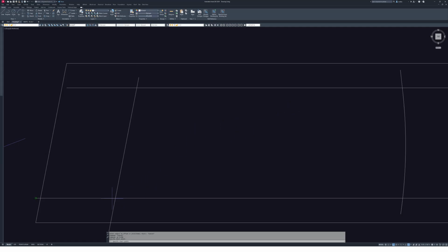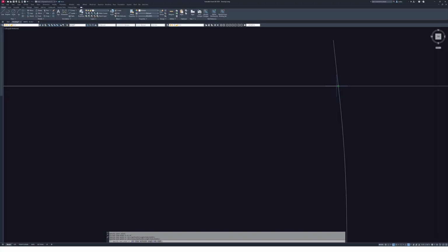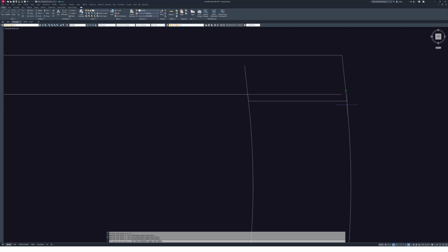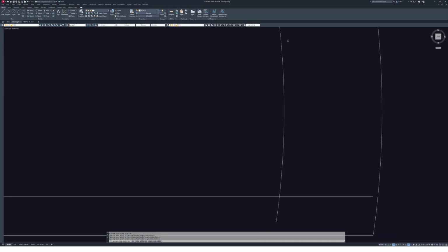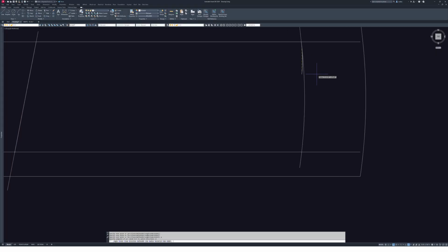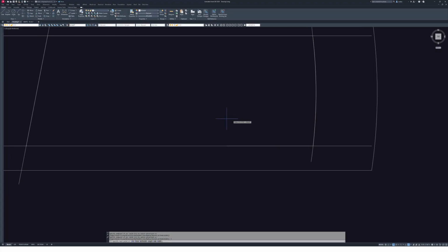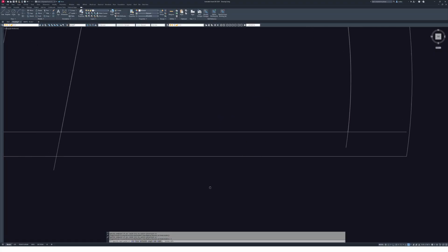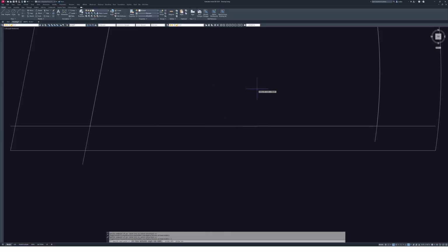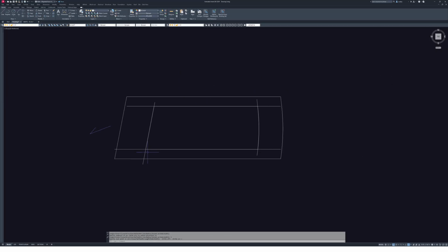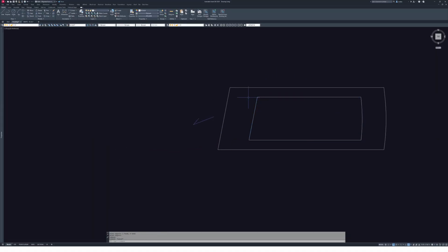I'm going to make a polyline and go intersection, intersection, intersection, and then find, that's the end point. So that's essentially this end point right here, offset down. Type A for arc, intersection, and then L to go back to line. See, I'm back in line mode, and then C for close. And now I can erase these offsets, and that gives me a polyline for my setback.